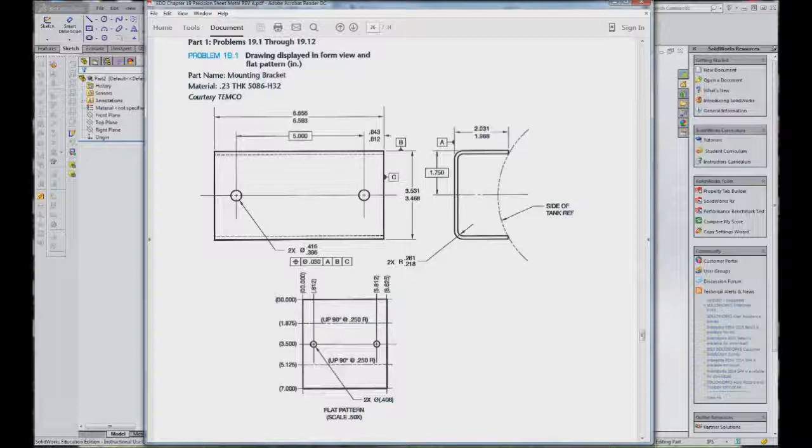The ones shown in rectangles are your basic dimensions. So 5 inches, it should be 5 inches. When you are drawing these parts, if you're given these limit dimensions, you will always draw them to the mean size. Okay, so you have to do some calculating. So again, this one here would be 6.625. This one here would be 2 inches. This here would be 3.5 inches.